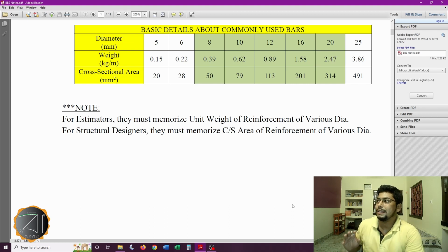Now I am not stating directly the tensile stress term, because we can use reinforcement for various aspects other than just flexural tension. We can use it as shear reinforcement, that is diagonal tension obviously. We can also use the reinforcement for taking up the compression in a double reinforced beam, and in the case of the column, we use the reinforcement both for taking the direct axial compression and also the bending moments.